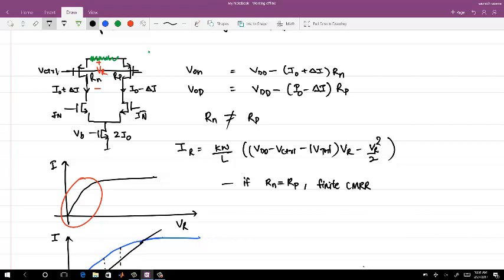It will not show up, because it is a common mode change. Your PSRR will be really good, excellent PSRR. You reject all the noise because it appears as common mode noise.